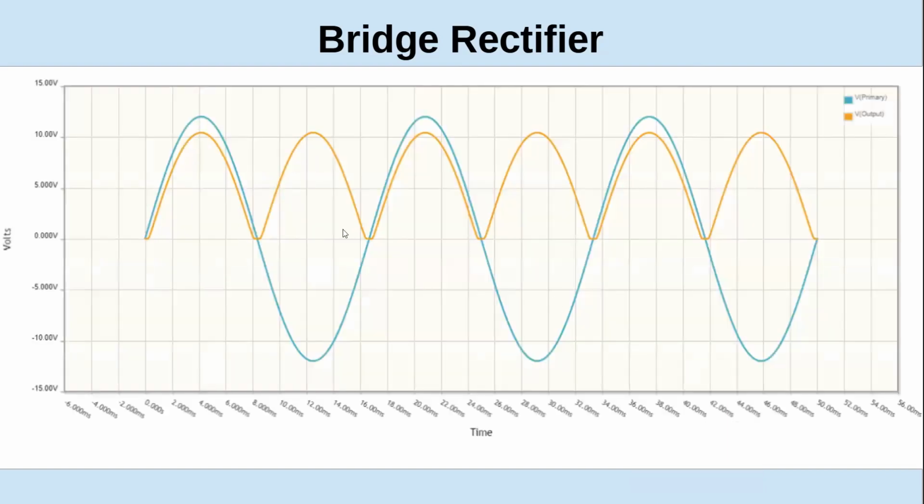And again, you get the same kind of output every half cycle. Now, if you notice, there's a little more loss than there was on the full wave, because of the resistance in the diodes. And because of the range, it's hard to see the 0.6 volts, which would be down here to pass the threshold, which is why you see this little flat spot. That's because it's not turning on at 0 volts.